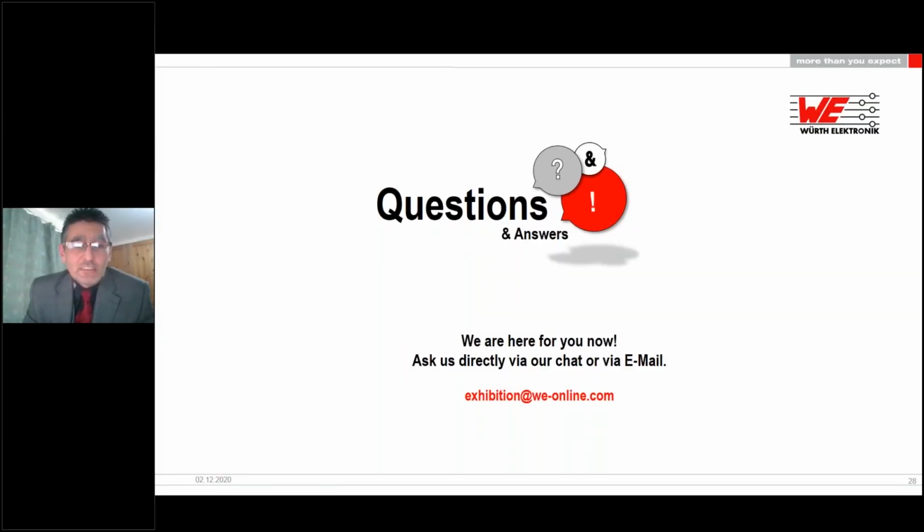But what I don't want people to think about, and you will see this if you decide to play with the examples I put in, is that you do not have to follow 40%. Sometimes you put 60% or 100% and you end up with a more suitable inductor for your design. So 40% is not a holy grail or an absolute requirement. It is, again, your degree of freedom.